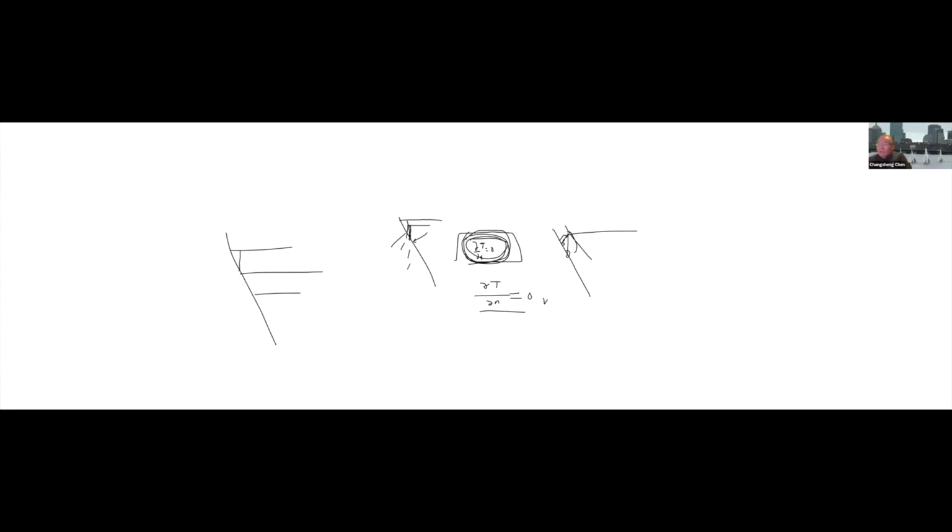That's called shaved Z. How can you resolve the flux inside that region? That's what we are doing, what the FVCOM team is doing: with shaved Z, we determine how the flux should be in this region, and the pressure gradient force in that kind of Z coordinate system.